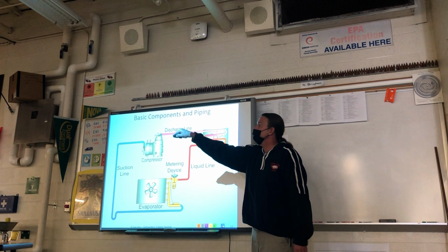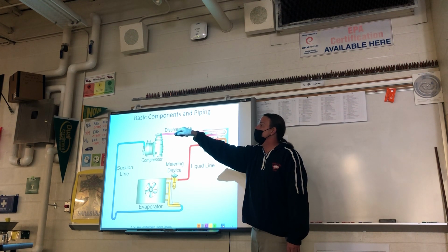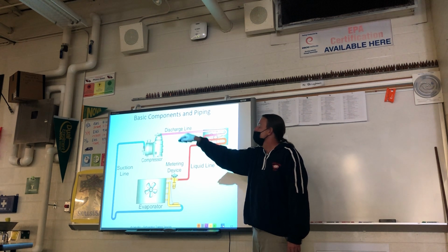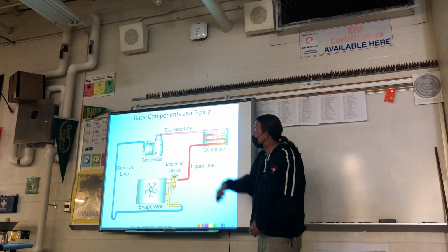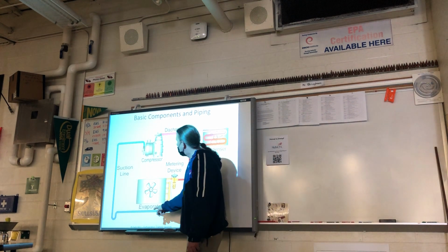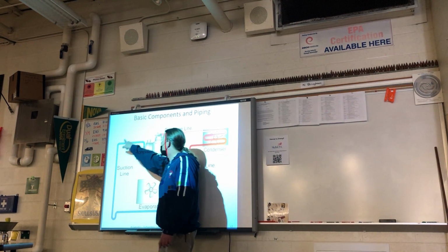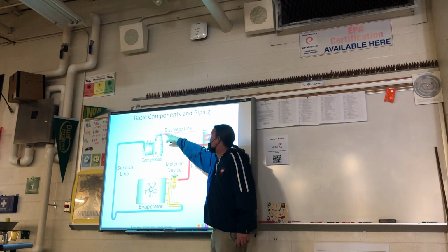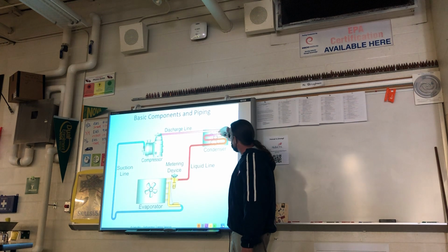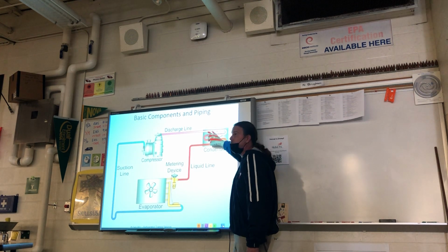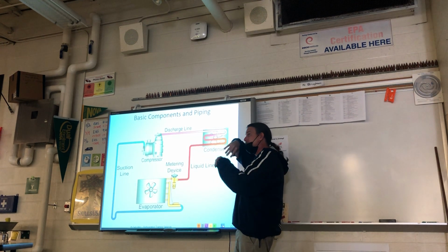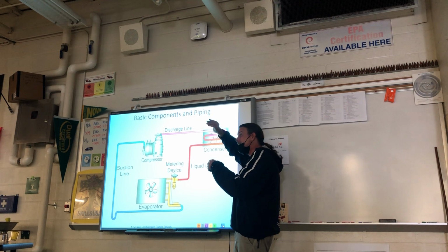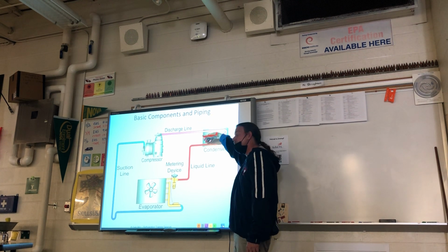In fact, there's one, if you take a look, on my condensate. Right there. And on some of those other units, there's a P-trap. If you look where the drain line comes out, there's one here on the refrigerant line. This is our oil trap. So you have oil returning back that flows. We want that oil that you put in the compressor. It's also mixing with the refrigerant and getting kicked out. And it's flowing with the refrigerant, and when it gets up against the pipe, they call that fouling. It creates a little bit of insulation between the pipe and the refrigerant, and we don't really want that.